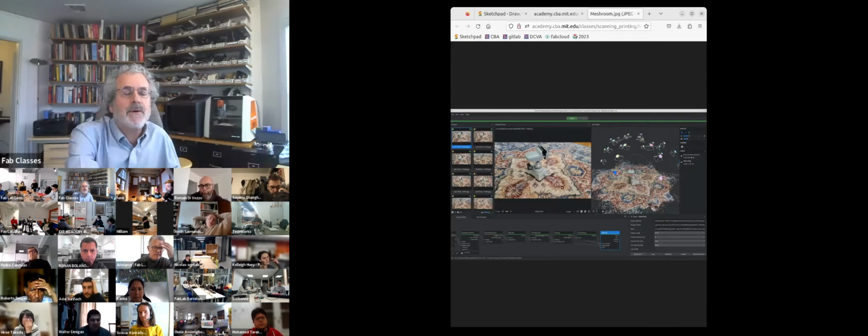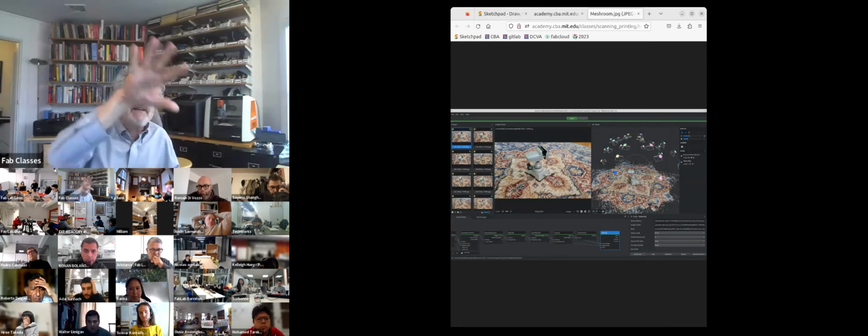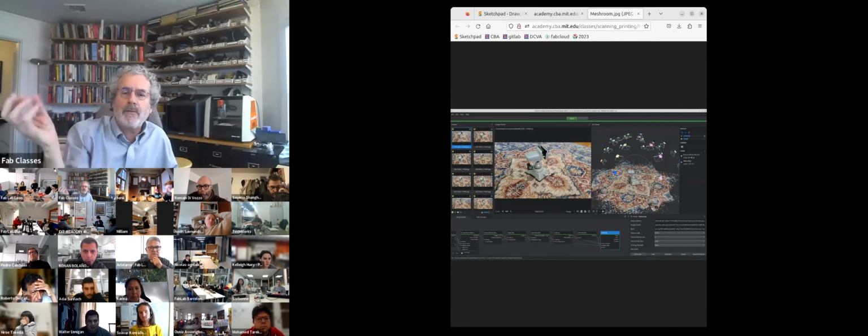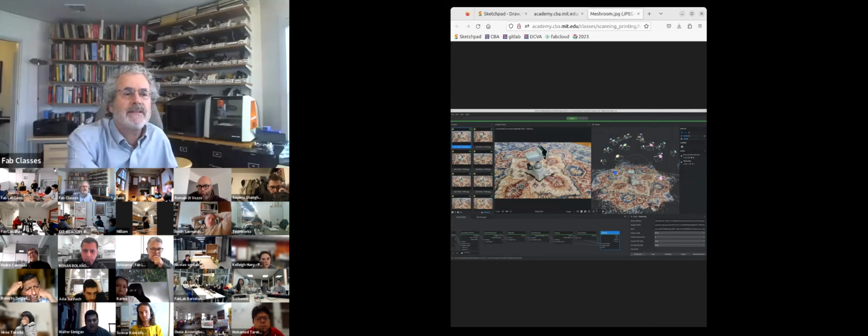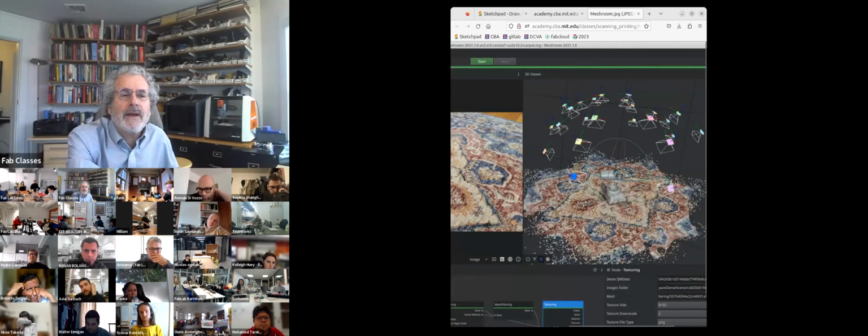And here's an example, I took this vise. I'm intentionally putting it on the carpet, and I'm using the carpet as the background because it has a lot of texture for the scanner to see. And I've got it lit fairly uniformly, so there's no shadows or bright lights. And then I just took a lot of pictures, and then you throw this at this tool. What it worked out here is where I took all the pictures from, and then it gave me a 3D model of the object I scanned.